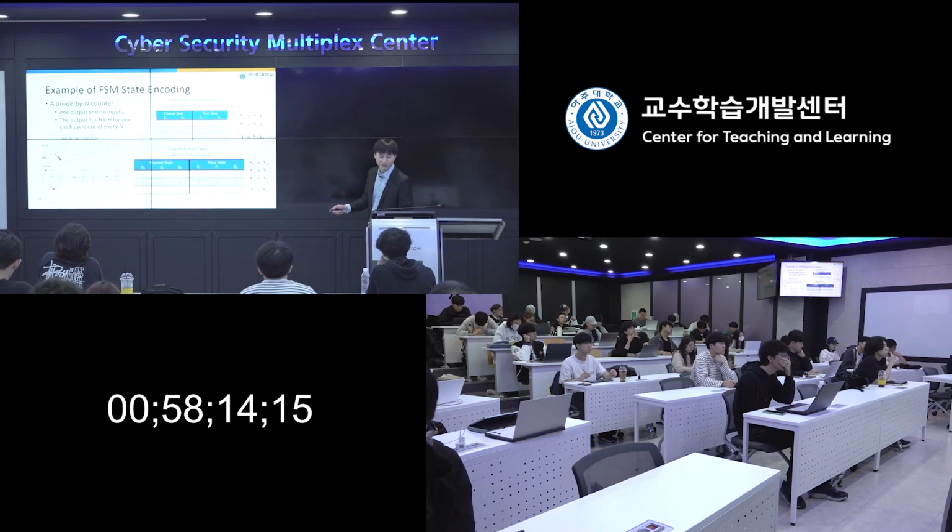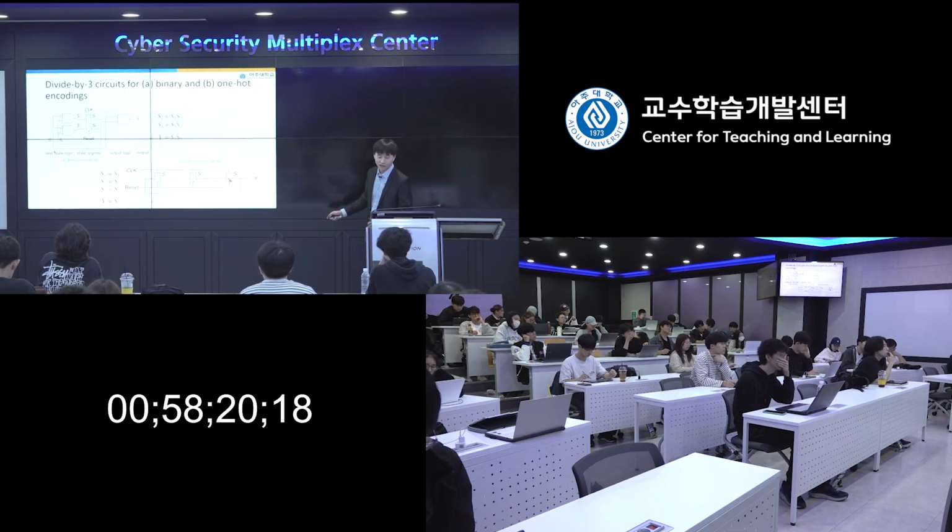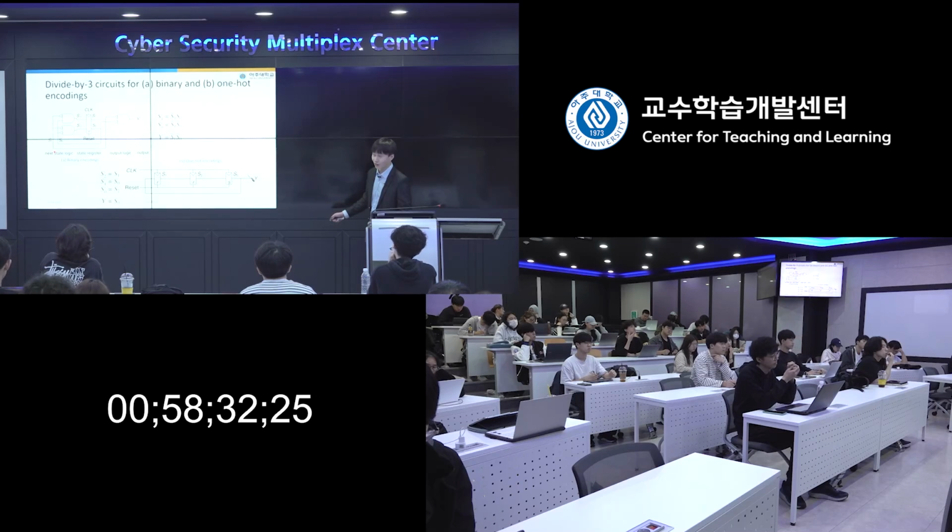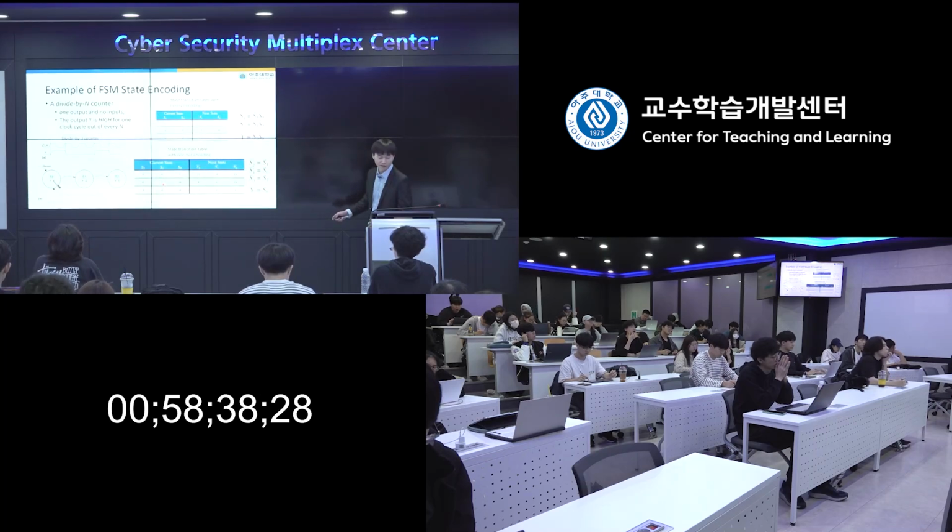Since this timing diagram starts from 0 to 1, that's why for the last register we use a settable register. Then when in the initial state, we can set the output to 1 and continue the timing diagram. That's from the design here.